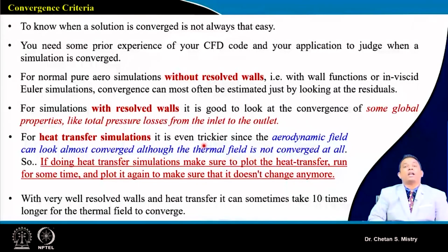When you put that in as an observed parameter, the fluctuation is what will get steady. Once it reaches a certain limit, it will give a constant value, and we can say my solution is converged. So that is one of the ways.